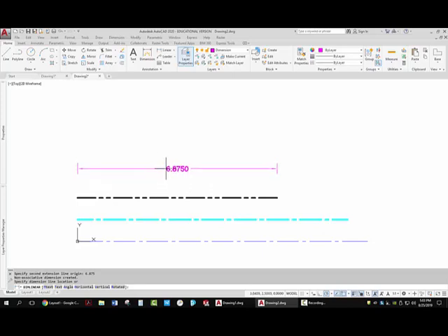But now I have another question. Where do I want to actually place it? The actual dimension started at the points that I picked, but it doesn't mean that the dimension line will be placed there. I have a couple possibilities. I can go back and hover over the end of this again and go up and type in 0.75. Now it places the dimension line itself exactly 0.75 inches away.